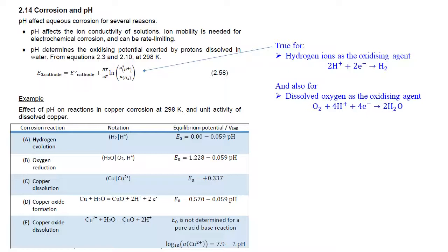But let's then come back to this first point. Does the corrosion happen at all, say in this strong acid? So the question about how pH controls whether corrosion happens at all, in other words, is there active corrosion, passive corrosion, or no corrosion because the metal is thermodynamically stable, the contribution of pH is explained by the Nernst equation as shown in equation 2.58.